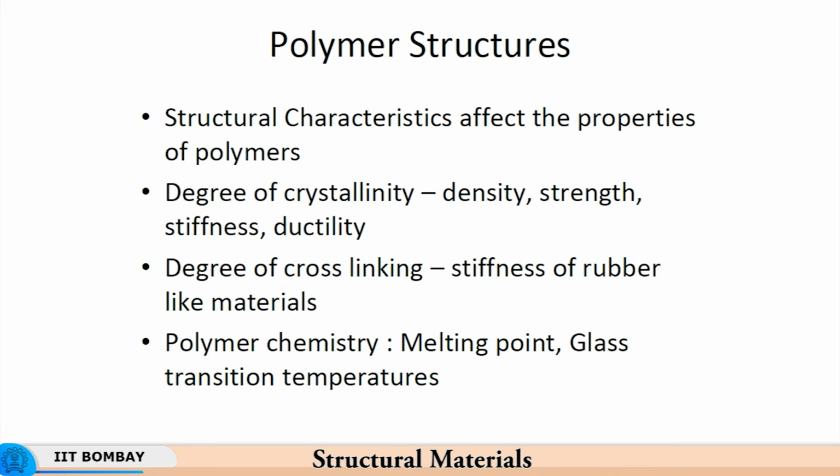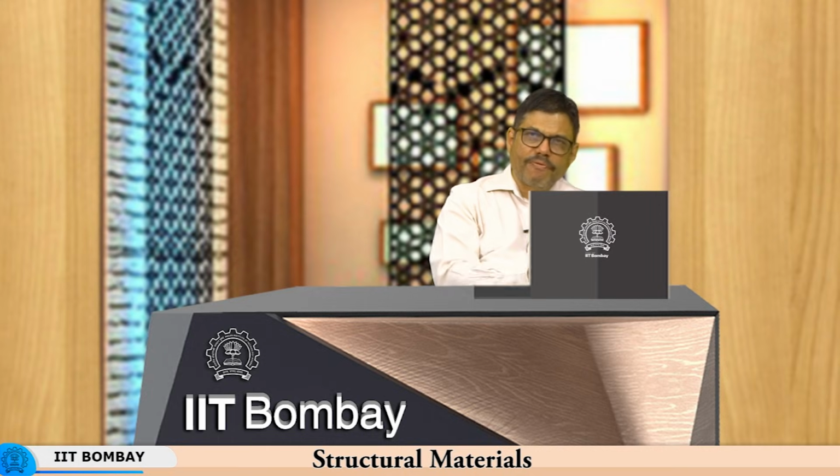The strength is very high, but then we cannot expect ductility from these, because now the mechanism of ductility is completely different in case of polymers. Now, unlike metals where we had dislocations and dislocation movements taking place, so that the material can deform, right. When a dislocation in metal moves from one location to another, you see that in the form of permanent deformation.